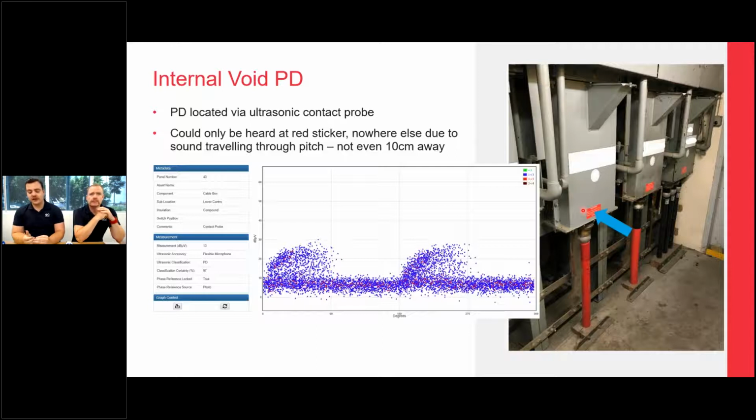That client then decided that as these are considered to be a higher risk on their network, they would de-energize the panel. They organised that about 2 weeks later, and due to the fact we just installed monitoring equipment on this board, we could actually see the second that they de-energized the panel, all PD sources disappeared from that panel, and the entire site became a lot quieter.